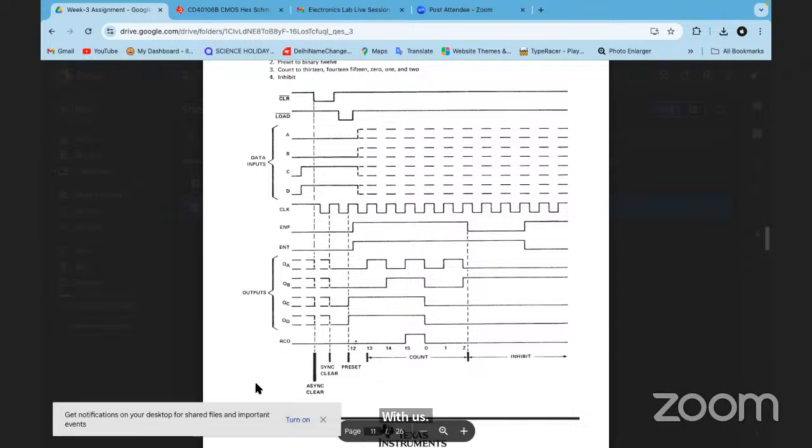Even though there are multiple things, it is clocking through one inverter, so it is only one TTL load. Yes. And another thing is, the amplifier which they are using is a very high slew rate amplifier. Those devices need to be carefully, finessely handled.